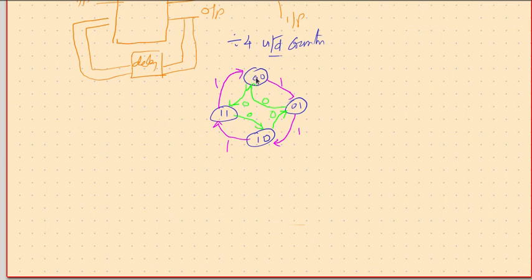So if I call these A and B, we have present state AB, and we have input up down bar, and then we have next state AB. And once we know that, then the excitation JA, KA, JB, KB can be identified.